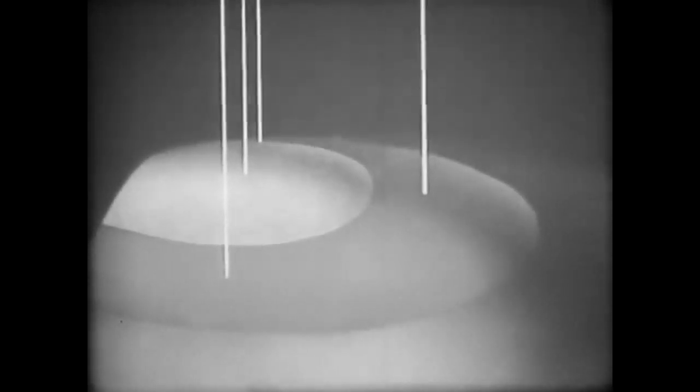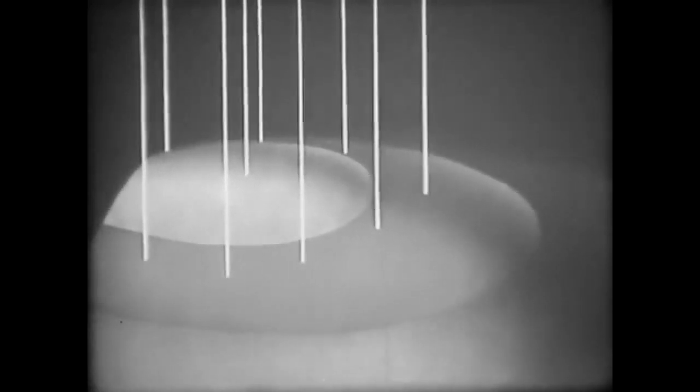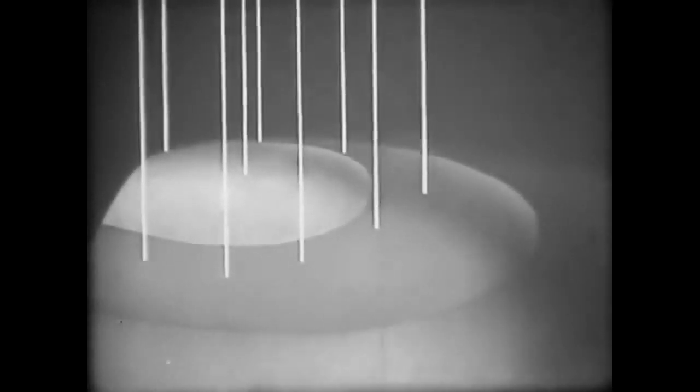To bring the oil field into full production, further wells will be needed. These are drilled into the oil-bearing zone beyond the edge of the gas, so we get the maximum assistance from both gas and water pressures in driving the oil to the surface. As more and more oil is withdrawn, we can inject water back into the structure to maintain the pressure by drilling more wells outside the limits of the oil accumulation.